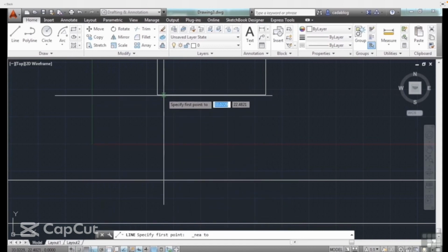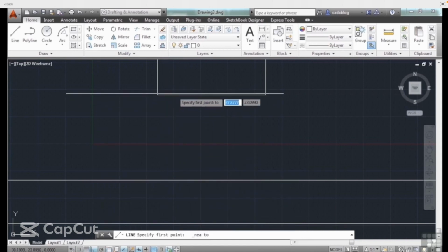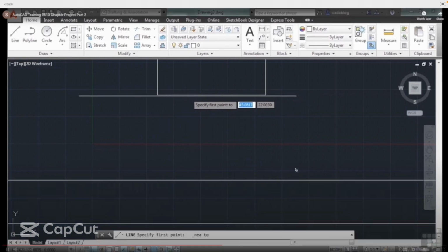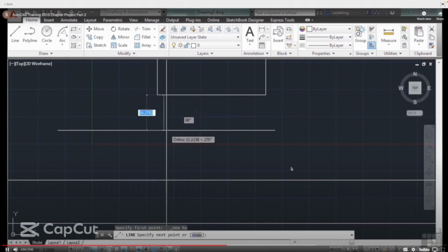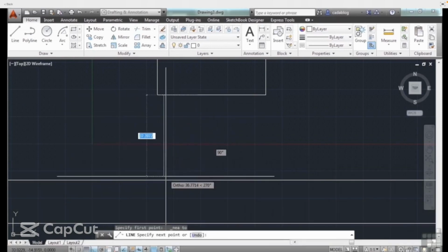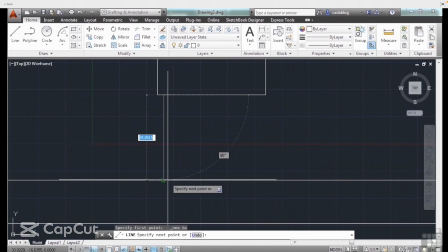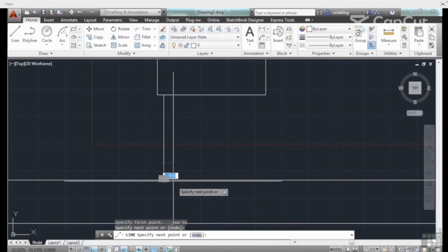And now we're going to be able to start our line right on any of the places we pick from our house. Let's put the garage on the left side here. Left click, and then draw the line. As you see, the perpendicular glyph is on. Our line will be perpendicular to our road, which is what we want.